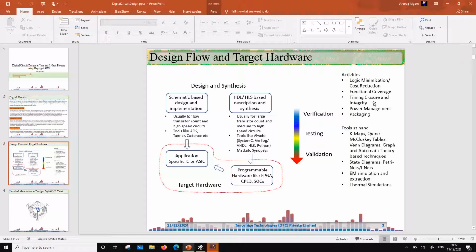Besides that, in terms of software, we have tools for doing parasitic extraction. Once you have done a circuit, all the components in the circuit are usually transistors. Very rarely do we use resistors in a digital circuit, right? In this case, the various parasitics of a transistor can be extracted by mathematical extraction, or they can be extracted through an EM simulation, which is a full-field solution, right? Usually if the circuits are large, we do not go for EM simulation, we go for some form of mathematical extraction of parasitics, right?